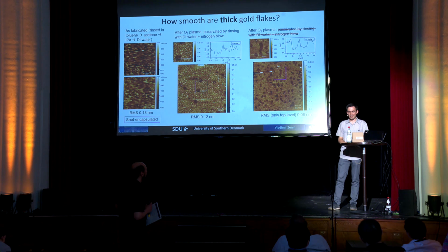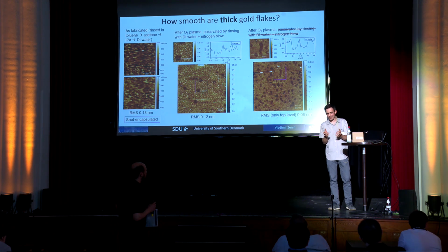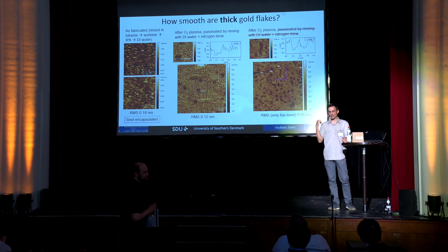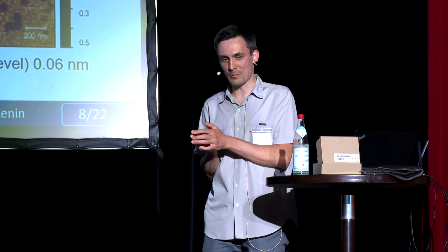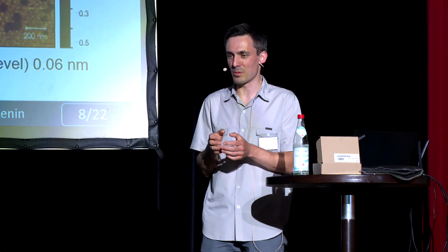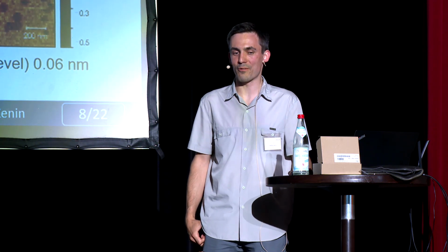Therefore, the surface is not so much different from flat. It can go just one level up and down, but not more. I haven't seen any funny shape there. Well, it can grow a funny crystal, but you just throw it out. But if it's grown as a gold flake, it's fine. Of course, whatever you grow, you go to optical microscopy and look in dark field and bright field, and see that it should look perfect there, first of all.